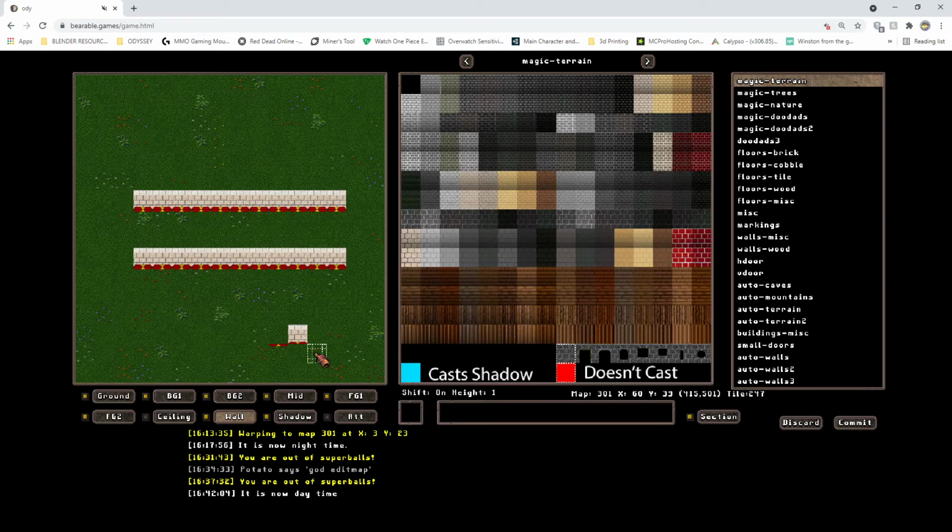Now, one helpful thing is that when you have that picked, like if I want to place this one, you can hold Alt, and Alt will lock in that particular wall direction, either X or Y, no matter where else you move the mouse. For example, let's say I want to go vertical. So we have our big box in the middle. I go to the left of it or to the right of it, depending on what edge you want to make. I hold Alt, and then I can drag anywhere, and it'll create an automatic vertical wall for me.